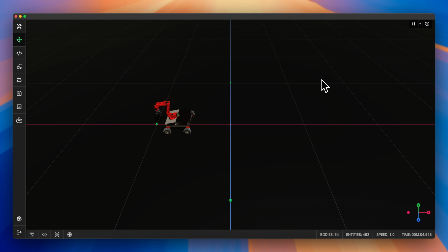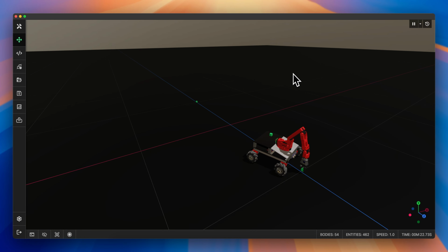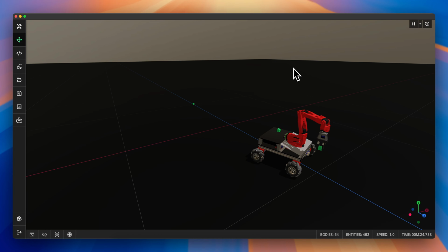Since the first link of our SO101 robot is based to the chassis, ProtoTwin can't determine what the grounded link is, since there are no joints a part of the robot controller that have a base set to null. This component may also be useful if you have a humanoid robot arm or a 6-axis robot moving along a track, and you don't want the robot controller to solve the link for the track, but would like to drive that link separately instead.